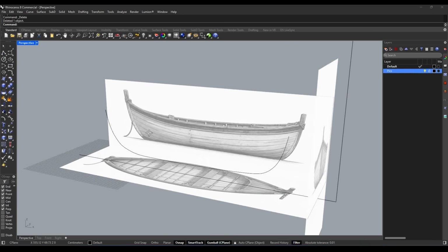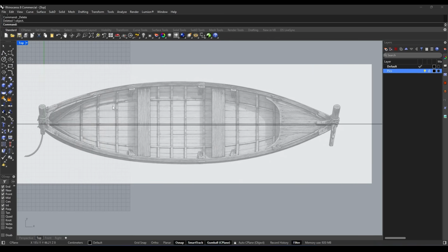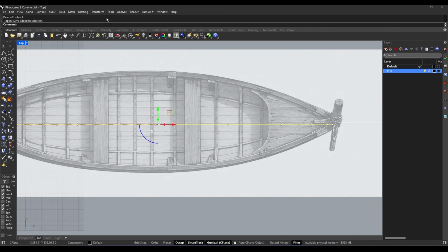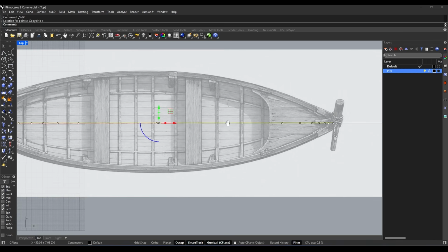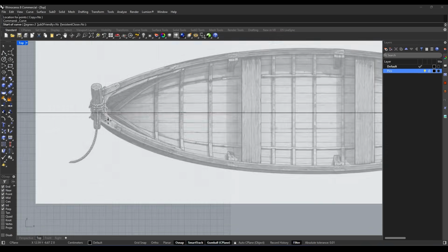If you notice in the perspective view that the curve is not exactly placed on the axis, select it and use the set XYZ coordinates command to adjust its position so all points are aligned on the y-axis. This ensures that the model is perfectly symmetrical from the beginning and helps us avoid problems in the later stages of modelling. Now, we'll move on to the second curve.